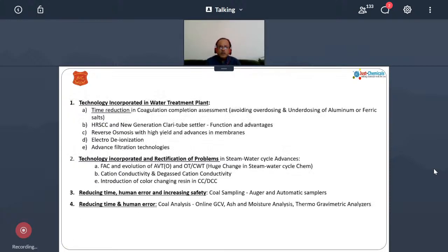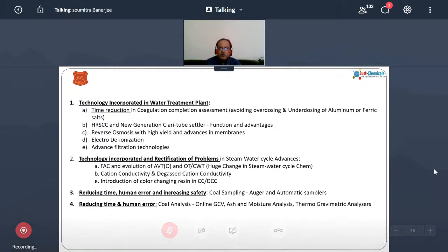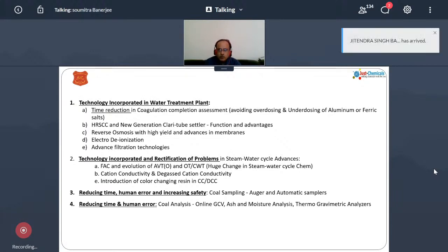Now, the technology and the changes we will be talking about today, from the past to the recent. One is the technology incorporated in the water treatment plant, that is, time reduction in coagulation completion assessment. We have to assess how much coagulant and how much flocculant needs to be dosed to clarify the water, and we need to avoid overdosing or underdosing of aluminum or ferrous salts,